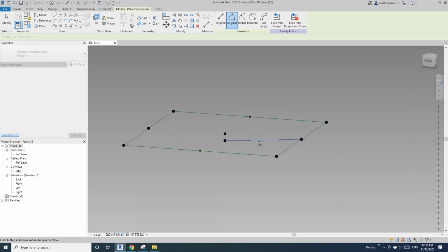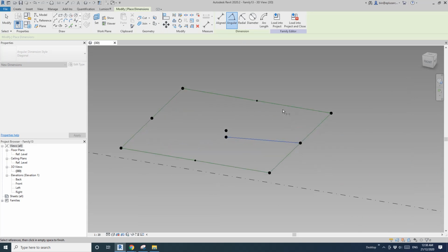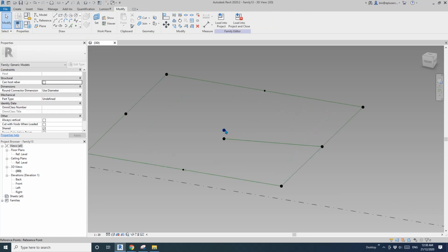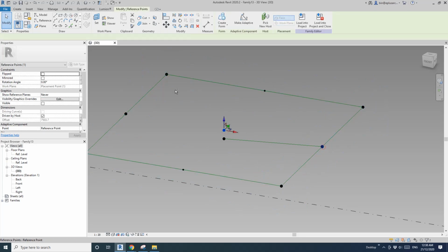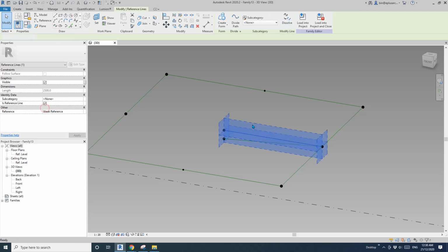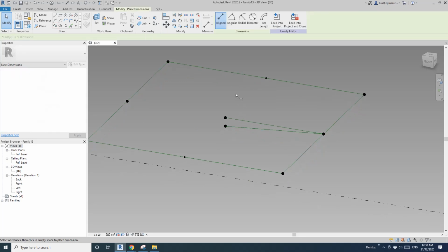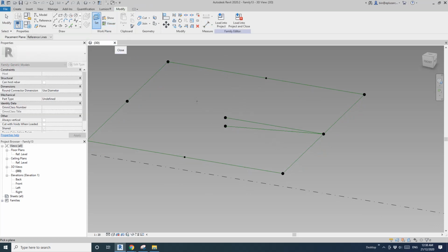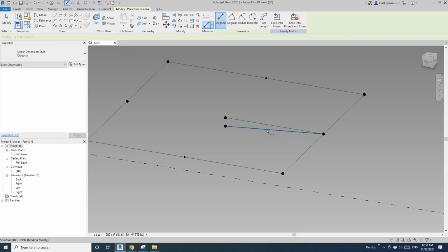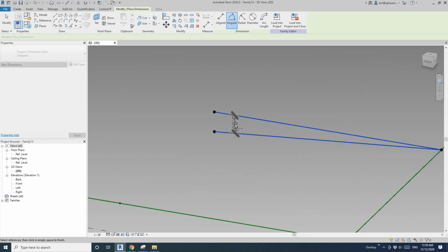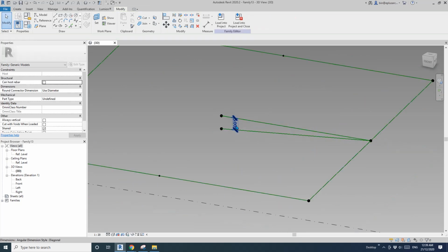It won't let me, so that's fine. I'll just do this one. So spline, reference line, and if I pick the set work plane first, and pick the vertical work plane of this reference line, dimension, angular, this. So you can see that's 5 degrees. Okay, 5 degrees.